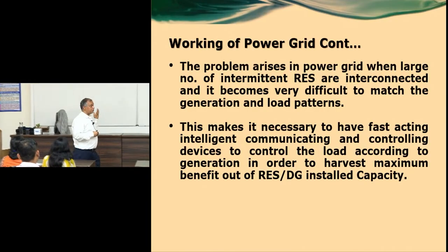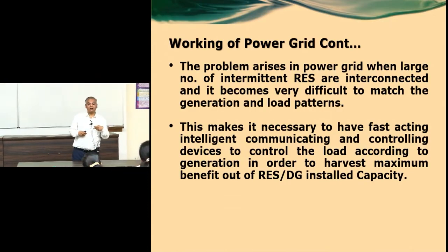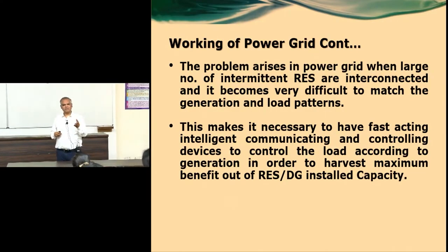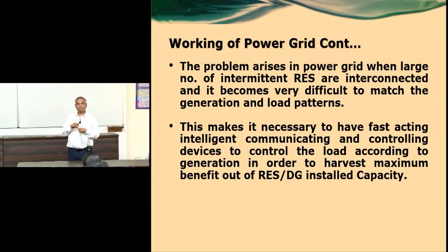So that kind of situation was there, and then we were working on a project given by Vestas and ABB, and at that time I developed a concept where the power electronic capability of the grid interfacing inverter can be utilized to generate sufficient reactive power. Because for reactive power generation at that plant's PCC, they were installing that reactor.